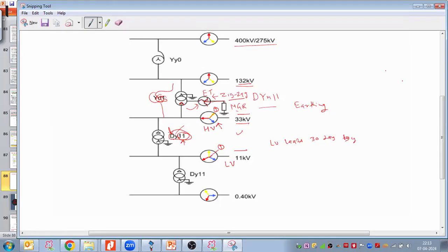So now I'm rotating 30 degrees, and this one will reach 12. Here they have 9 o'clock, so this will come to 8 o'clock, because the entire diagram has to rotate by 30 degrees. Similarly, this will rotate again, it might be at 6 o'clock, so it is coming to 5 o'clock like that.